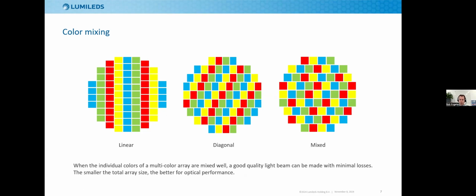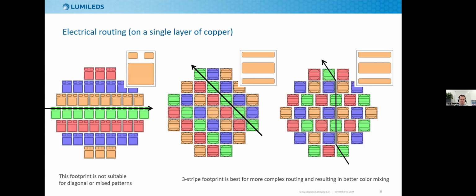So whatever we choose, let's put the LEDs in a randomized fashion. So how to do that and also be able to turn them on. Here I depicted 2 different popular footprints of LEDs. Here on the left, there's the Luxeon ZES, which has a large thermal pad and 2 electrodes for connecting the LED. This thermal pad is isolated, and it's large, so you would think, well, this is ideal for my thermals. But the routing is very difficult.